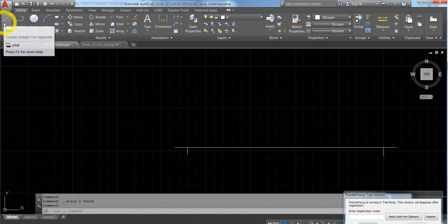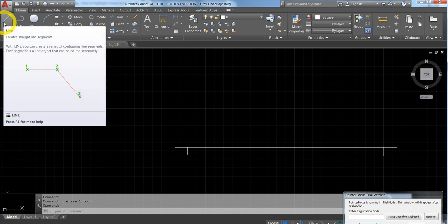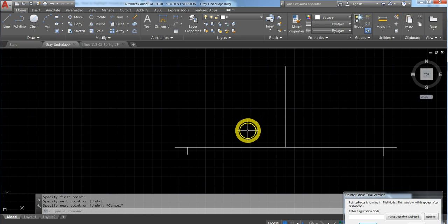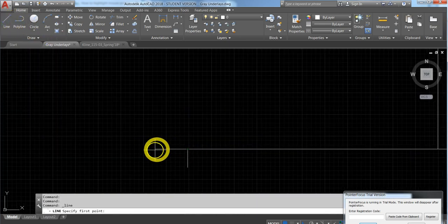So a number of different ways to do this. I'm going to show you, which I think is the easiest way. So with my O snap turned on and midpoint selected, I'm going to find the midpoint of this line and just go ahead and draw it up. And now I'm going to zoom in on my bottom left corner. So now again, this is just my slope.